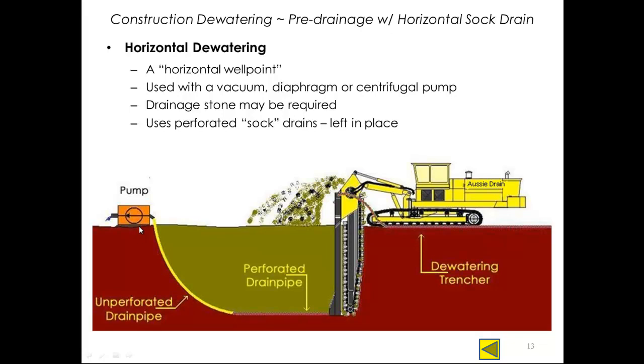This is connected then to a vacuum pump normally, and the water then, just like a well point, is withdrawn by vacuum and discharged. When the work is done, the pipe, because it's low cost, is simply abandoned and left in place.